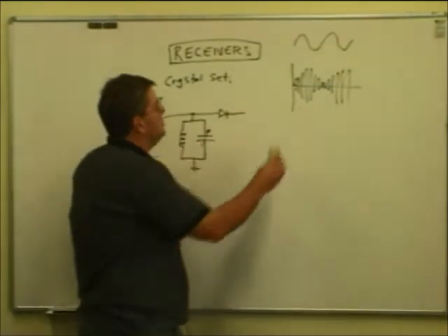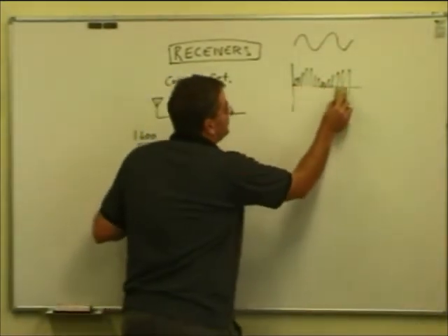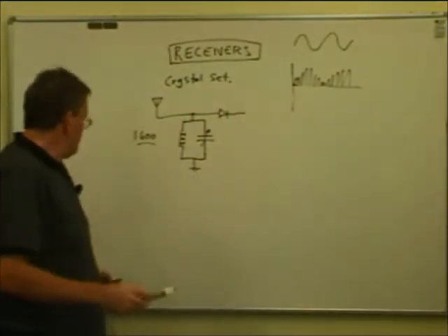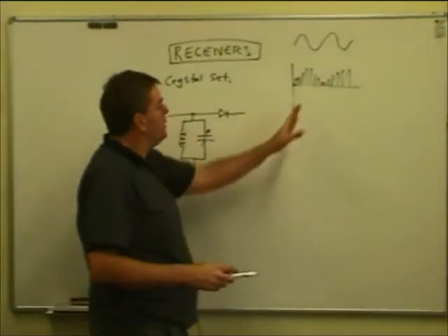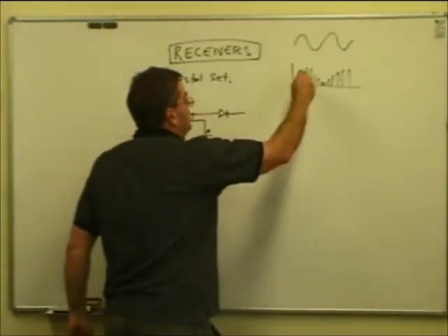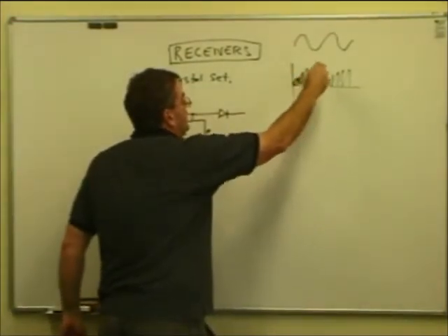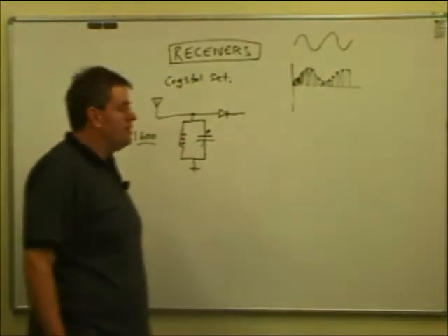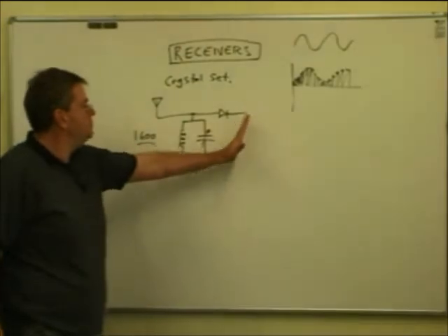So the first step we do, just like when we come on to power supplies in a bit, we've now removed the other half of the signal, if you like, and now we're left with pulses of carrier and the general shape of the intelligence. And that's what's at this point here.